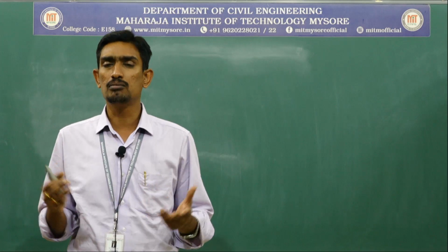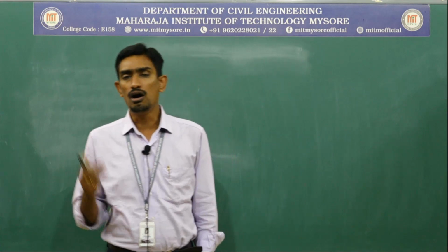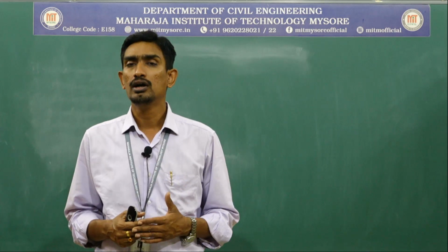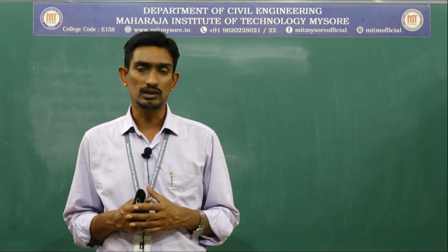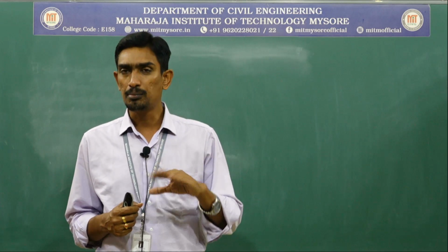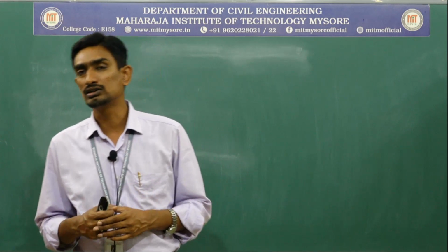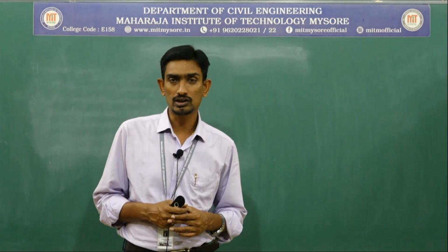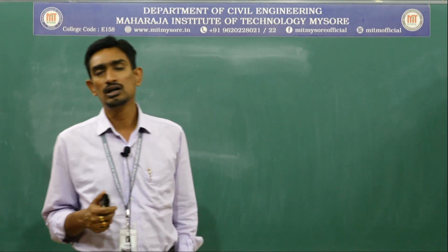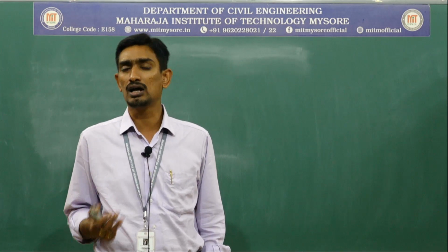Nowadays there are a number of companies coming up, that is Ultratech cement, Zuari cement, ACC cement. All these people are now looking into the go green concept. Even JSW, everyone is looking at the go green concept. Is it clear? That means try to minimize carbon dioxide by replacing with industrial waste. By this we can achieve the green concept, or reduce the carbon footprint. So this is regarding the cement. In order to manufacture the concrete block, we can use OPC or we can use PPC. If you want to go with a green concrete block, go with PPC.